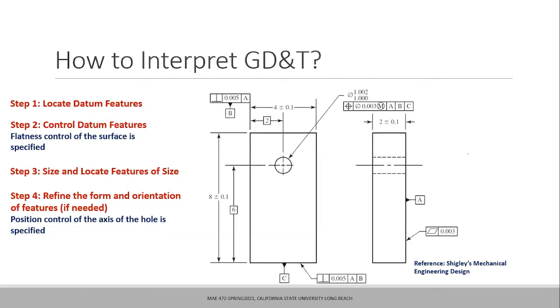Just to make sure I have this understood properly, if the inner diameter was manufactured to be exactly 1.000, would the bonus tolerance be 0.005? Yes, you are right. And why is it?